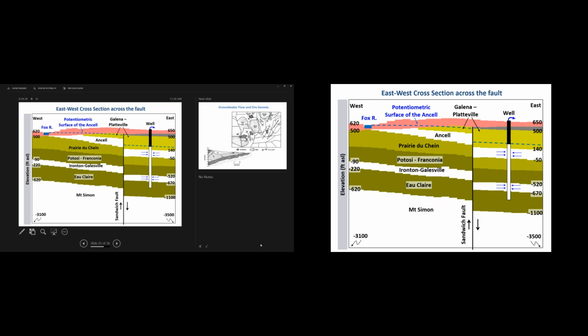Right. Yeah, and I guess that's what I'm trying to understand: you can replicate the offset with the elevations, but to replicate it, you have to go a step further and replicate the change in conductivity between those two. You have to replicate the effective resistance here. Right. And the interesting thing is it's not no flow, like it may look here. There is flow that goes from here to here. Yeah, vertically. It's just orders of magnitude less than what we're dealing with, at least in the horizontal direction.